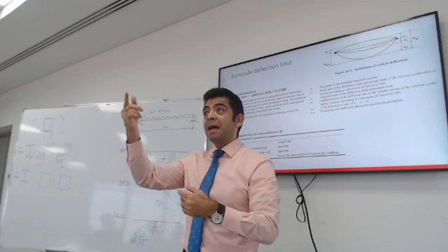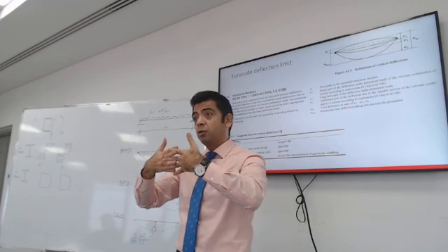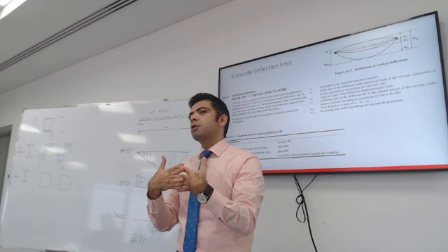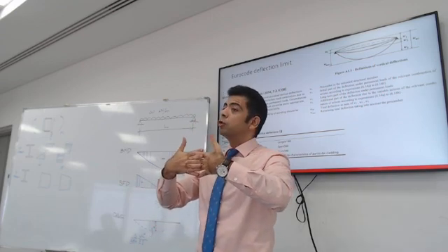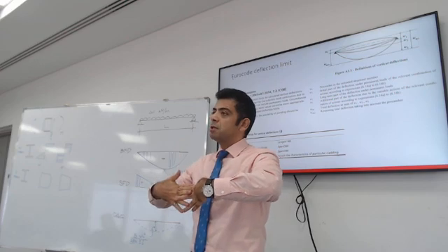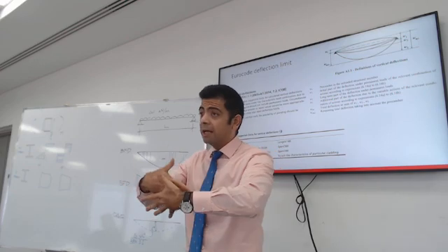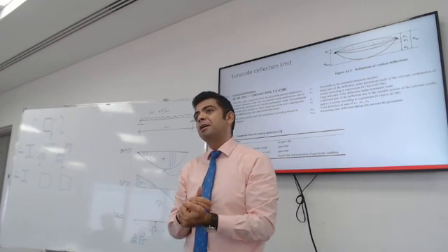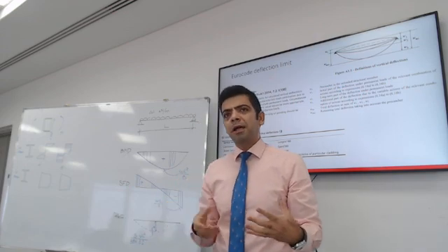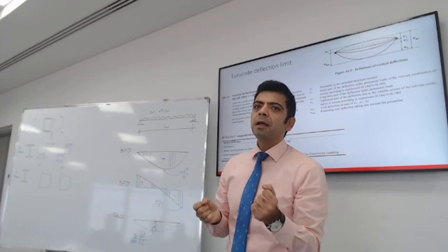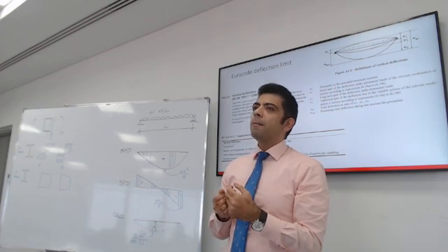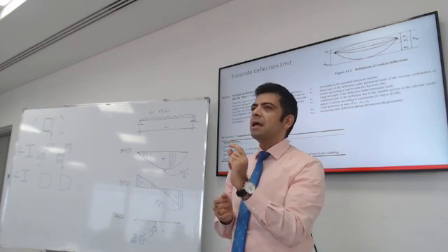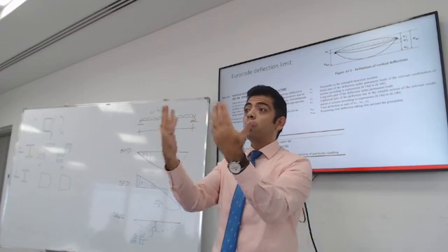If the beam has a window attached to it, or a non-structural element that could be damaged, the code says do not allow this beam to deflect too much, otherwise it will break the non-structural element. So what do I mean by a non-structural element? Windows. A window is not structural, despite you might look at it as supporting the wind.